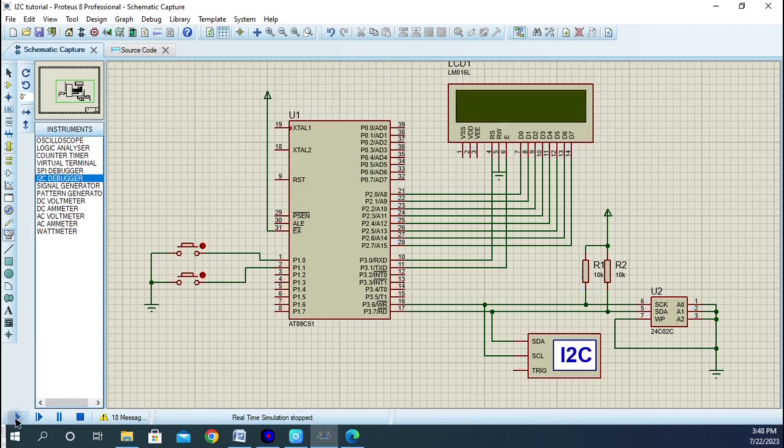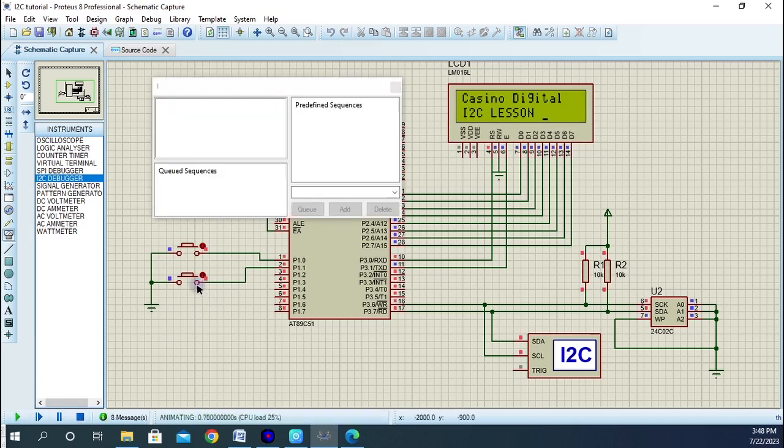Let's say I power on again now. I will just read directly without saving. You will discover that that value will still be there. That is why we say that the I2C EEPROM memory is non-volatile. You don't lose any information that you have on it. It still remains there until you erase it by yourself.